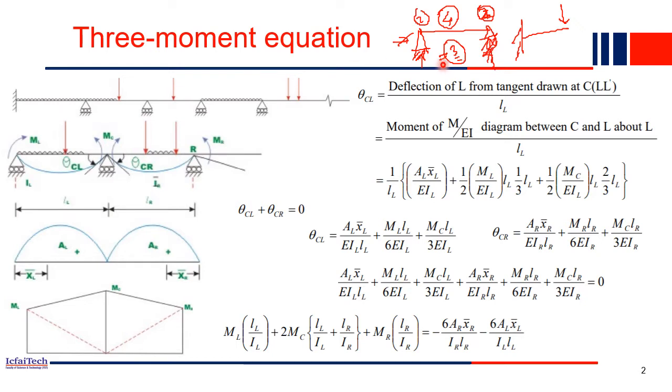Similarly, if you have a continuous beam, like if you see this beam, you can recall. If you visit the university, you will find all the beams are basically continuous beams. So here you have one column which is fixed, then here another column which is maybe roller, another column, and a single beam is continuous over all the spans. So we call this a continuous beam. So this is an indeterminate structure. Continuous beams are normally indeterminate in nature.